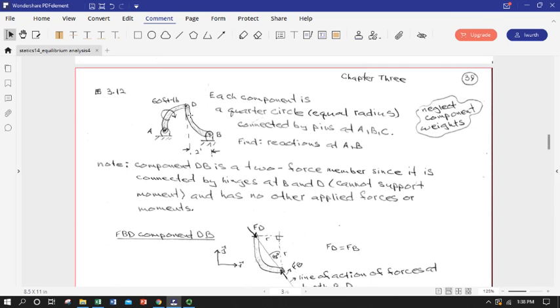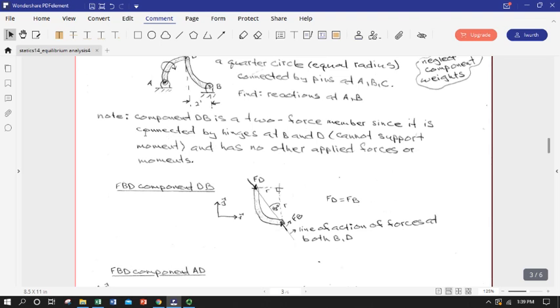So things can move at the hinge. Generally, the point of application of a couple isn't important. This time it actually is, because we have something that doesn't necessarily transmit moment. So hinge D. The moment is everywhere similar all over this member, and then this couple moment would be transmitted by forces applied at pin D across D to B. Okay. Apologies for the confusion. So that's kind of the key to getting our additional piece of information that we need to solve the problem.